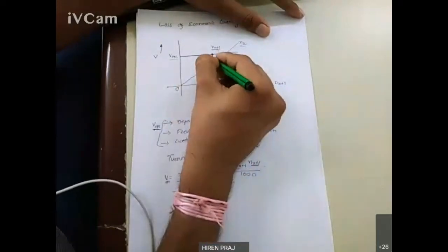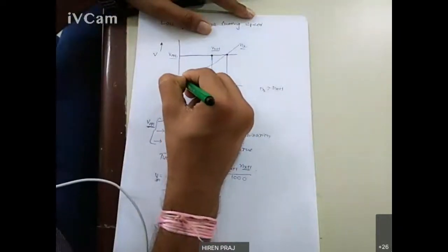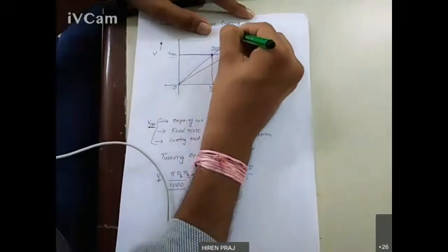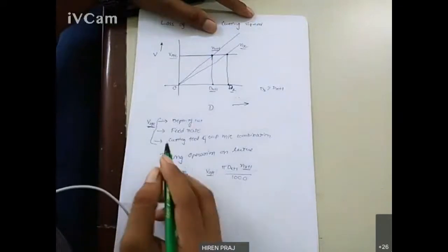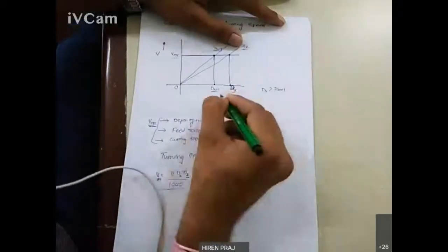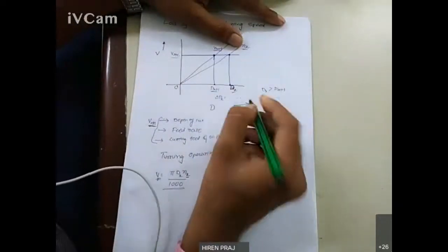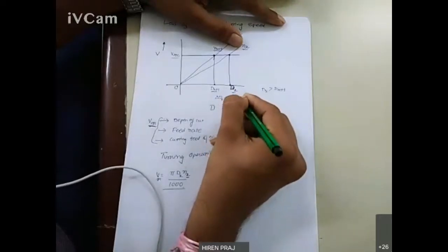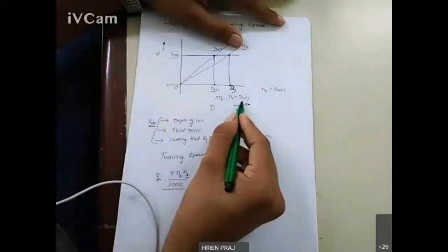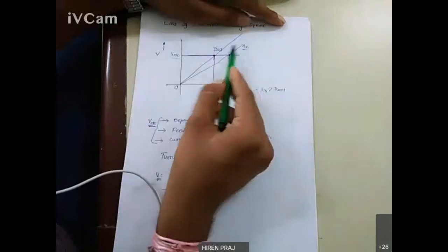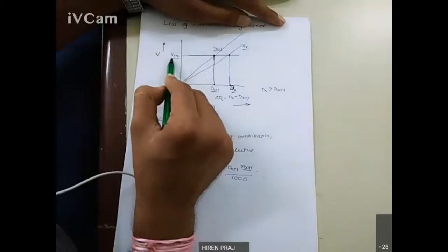Now again if I indicate the next line, then this line is for Nx plus 1, right? And the difference between these two, in the previous session we have seen, delta Dx is Dx minus Dx plus 1. This is the diameter difference which is to be removed to change speed from Nx to Nx plus 1 in gearbox, so that you can cut material at optimum cutting speed.